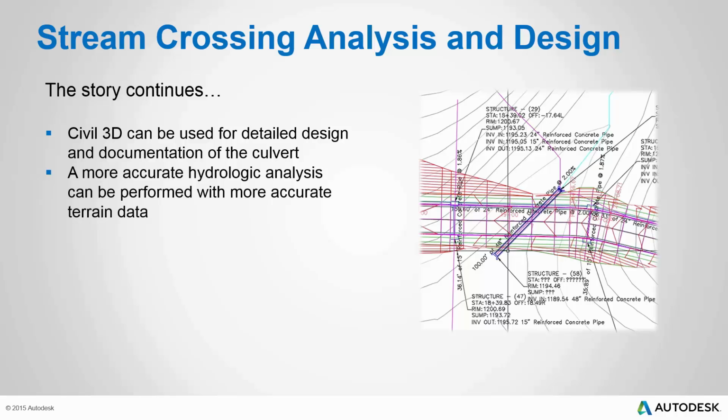Again, maybe the scenario is we do that initial culvert design in InfraWorks 360 where we haven't done a survey yet, and then later on we can check that and validate it with accurate terrain data in Civil 3D once we've acquired it.